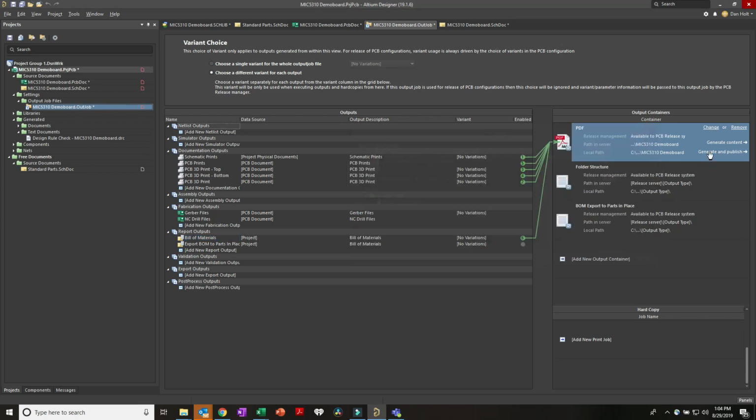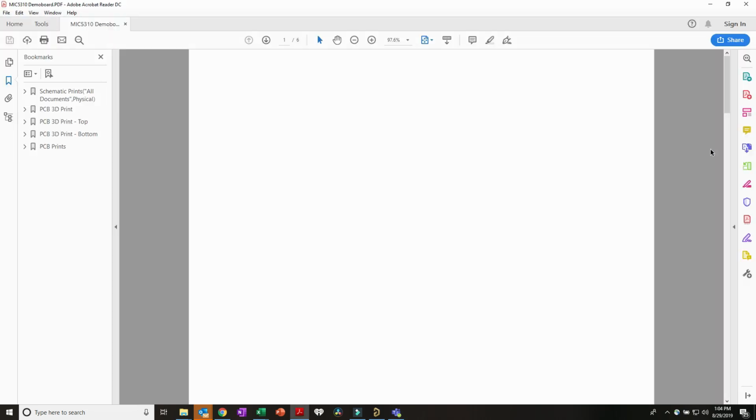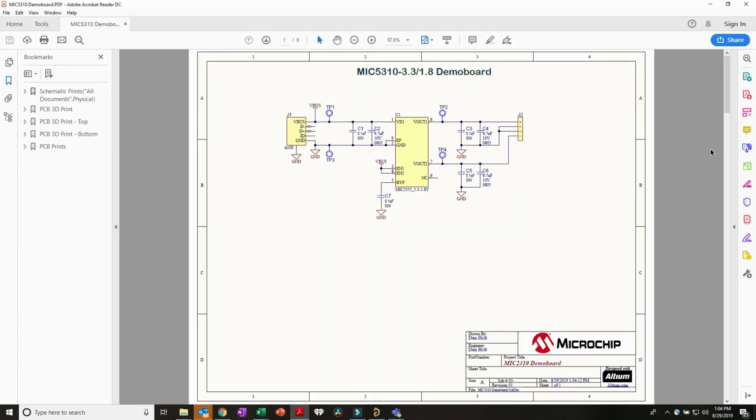Depending on how complex the board is, this can take a fair bit of time. It has to pull in all the information and filter it. It has to create all the 3D views. The beauty is you end up with a really, really nice PDF. In fact, you can generate a version of the PDF that has 3D views of the board, which lets the person actually flip and rotate the board around.